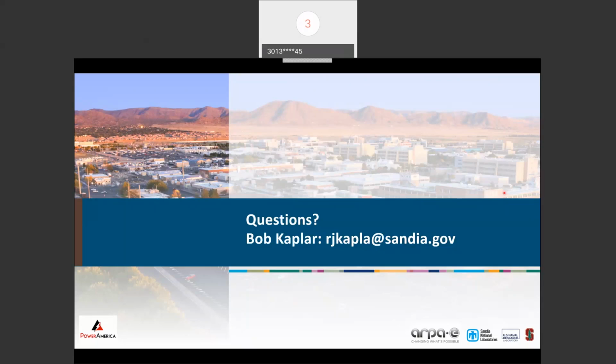Okay, next question. What is the typical size of widely available bulk GaN substrates? Also, what are the future prospects of bulk GaN in your opinion? Yeah, so again, we've looked primarily at the 2-inch wafers. You can get smaller pieces, square centimeter, 1 inch. I have seen some marketing type stuff from some companies saying they're up to 4-inch. I haven't actually ever seen one myself, but I think it is improving.